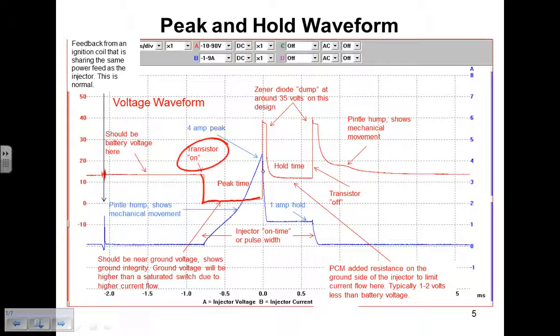And I think about it like this. When we talk about sensor grounds, I always give you a number, 100 millivolts or less for a sensor ground. And the reason I give you that number is sensor grounds don't carry any measurable amount of current flow. You're talking about microamps of current on a sensor ground. So can you think of that ground really being loaded with current and heat? And the answer is no.